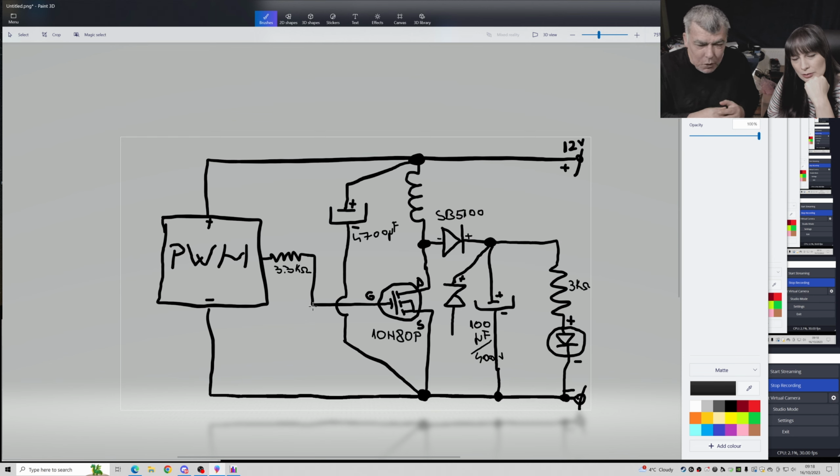Can we do it? What can we connect on the gate? The minus from the diode? Yeah, but nothing will happen. The moment the voltage goes over 15 volts, the voltage will pass and you will send 15 volts to the gate. That means the MOSFET will drive like full power.